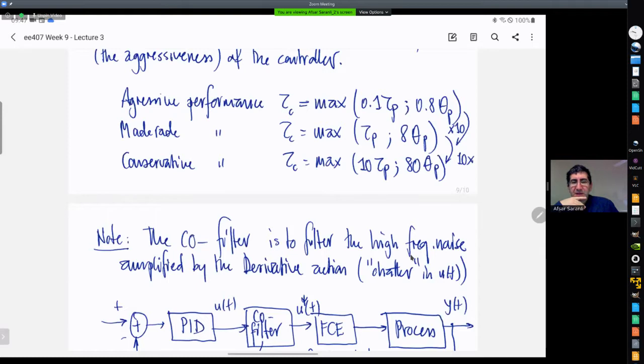The way we treat these systems is that we bring them around their operating point, and then we apply essentially a step input, and we observe the behavior around the operating point, assuming that any controller that we would design would also be operating around this nominal or operating point. So we apply a step input to the system and observe the response. If you observe the response to be linear, you can try to fit a linear model to it.